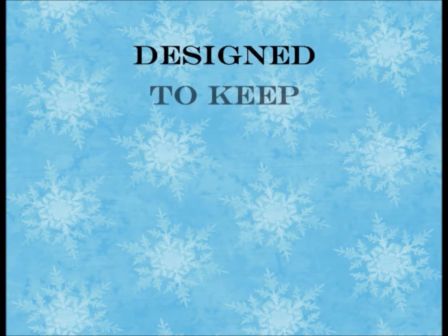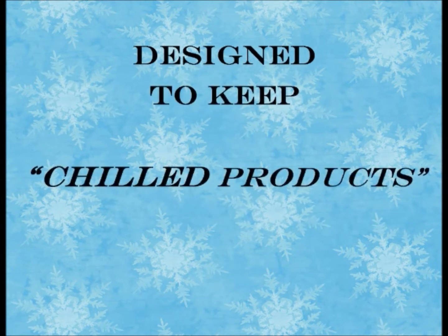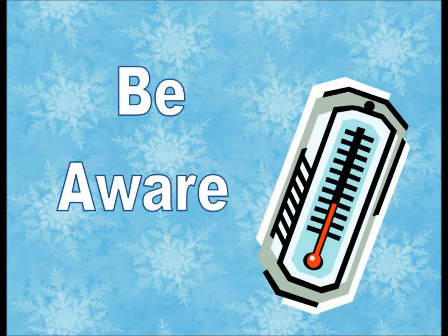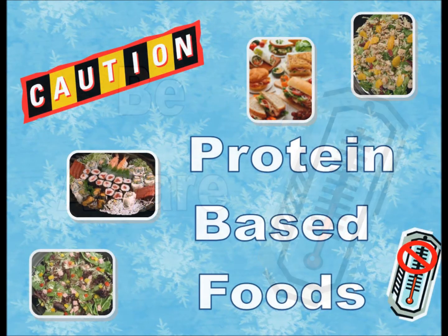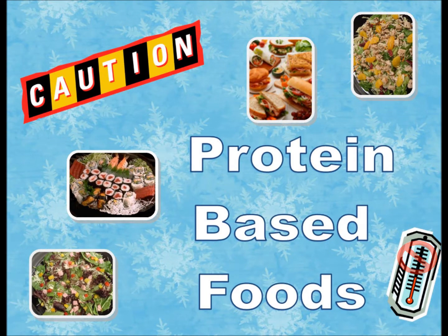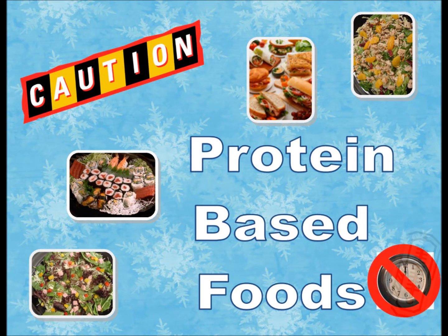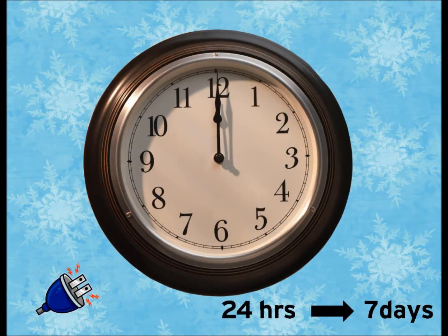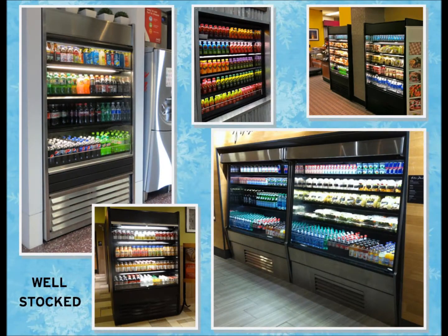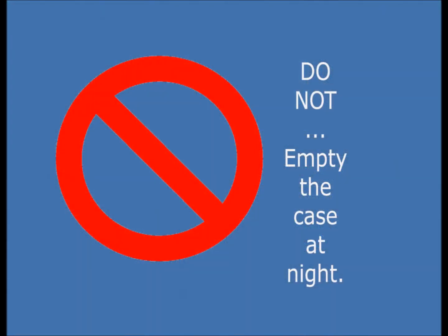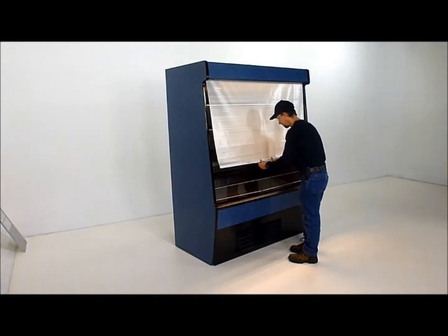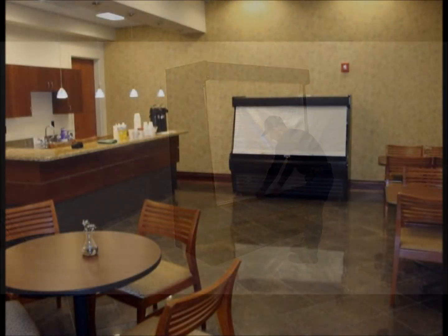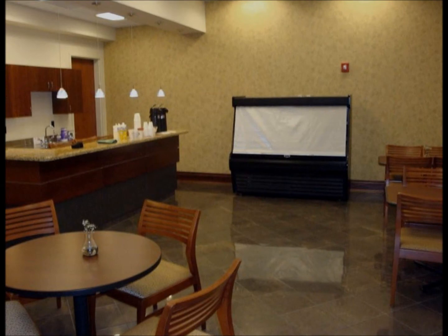Our cases are designed to keep chilled products cold, not chill products. Be aware that the case will not pull protein-based foods down to required temps in a safe time frame. These cases are designed to remain on 24 hours a day and will run best when well stocked. Do not empty the display case overnight. If you ordered a night curtain, pull the curtain closed at the end of the day and keep the display running.